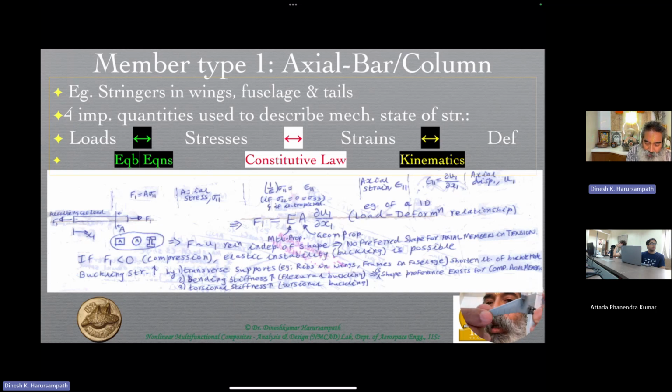So this is something that is important to be taken care of. You should know based on the relative orders of magnitude of torsional stiffness and bending stiffness, and also bending stiffness in two different directions: bending along the chord, and bending about the vertical axis, which is because of the drag. One of them is dominant because the L by D ratios are larger than one.